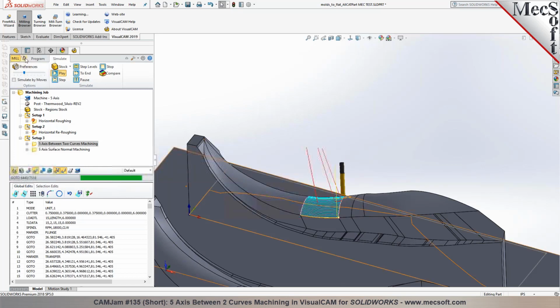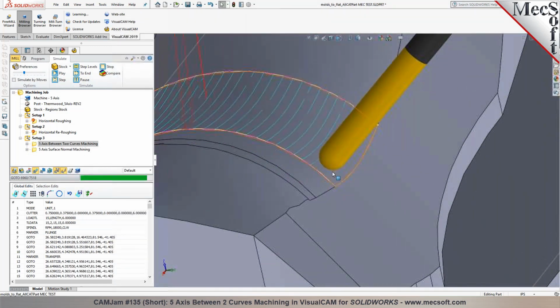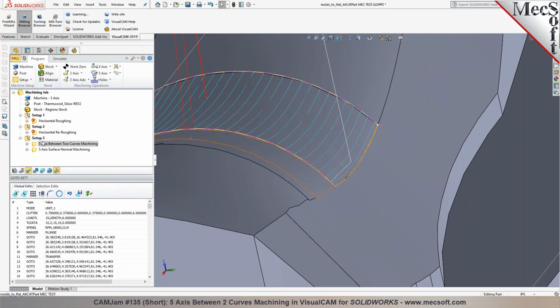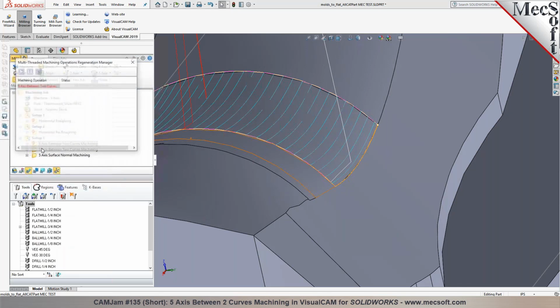Yeah, so let's go back and swap the tool out here. I'm going to pause this for a moment. So you can see the contact point, the tool tip is on the surface, right? Now let's go back and I'll stop this, switch back. I'll make a copy of this operation in here, and I'll go ahead and swap this out with a 3/4 inch flat bit. Just grab this flat bit, drag and drop the operation on it. Oh, wow, you can drag and drop like that.